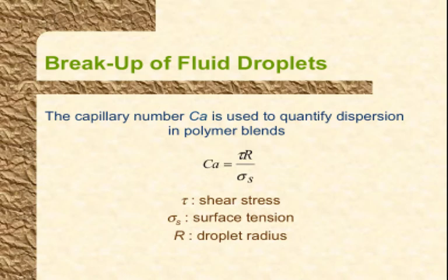There's a surface tension that wants the droplet to remain by itself instead of dispersing into the next polymer as a liquid, because you're dealing with two liquids. So surface tension is just like a cluster term. There's something holding one polymer together, and there is an applied shear stress that wants to disperse the polymer in the second polymer phase. This is the case of blending two different polymers.